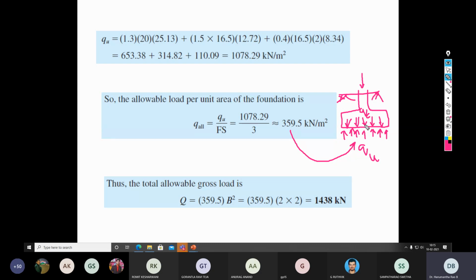If QC is higher than QU, then the soil fails, and that means the entire structure fails. Most of the time people ignore this small, simple verification. If you look at any report, this is given the least importance. You should not do that. You must always take the soil condition into account.